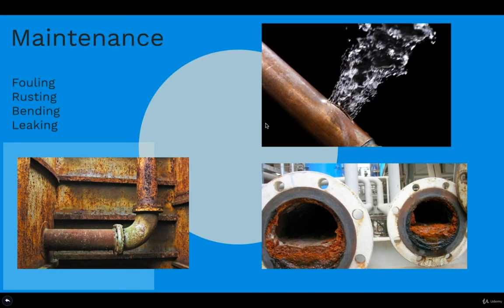So the importance of maintenance: well, they can break depending on the pressure they operate at, also if they get rust and so on. Talking about rusting, well, this concerns the outside fluid. If you have a pipe exposed to the air or to water, maybe ocean water or river water, lake water, and so on, they will get rusted because they have access to oxidation or corrosive materials, mostly oxygen. They can bend depending on the load, maybe even because they are not well designed, and they will leak.